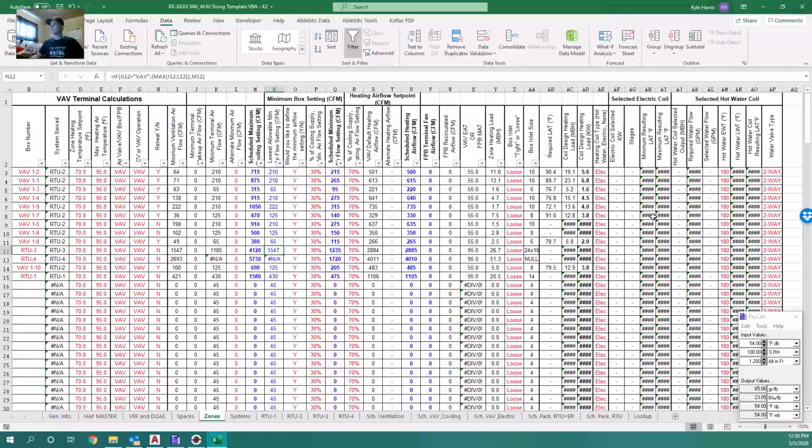All right. So this is telling us that in order to heat the space and meet the envelope load, the required leaving air temperature is right here. And that's based off of this number, which was imported from HAP. This is the heating MBH. And this kW is based off of what your entering air condition is, and that delta, your entering air, which is 55 coming out of the unit, and heating that up to what's required. So that is 5.6 for this one.